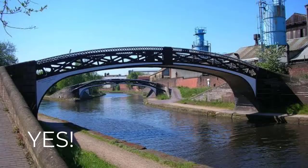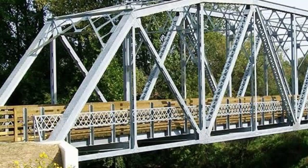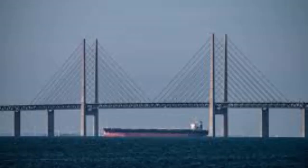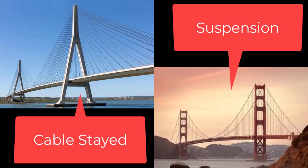There are several types of bridge, which may include the beam bridge, that is the most common type of bridge, and an example is the box girder. We have the truss bridge, we also have the cable stayed bridge, and we have the suspension bridge. Meanwhile, there is always a misconception, or let me say a mix-up, between a cable stayed bridge and a suspension bridge. And why is that? It's simply because both bridges have similar working principles. They are both supported by cables and they both have towers. So here are three differences between a cable stayed bridge and a suspension bridge.